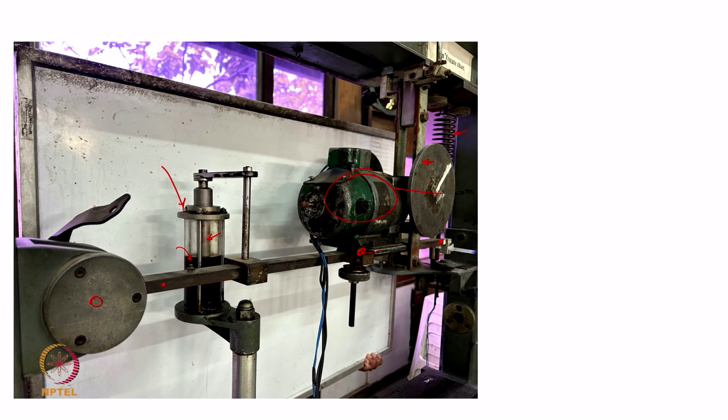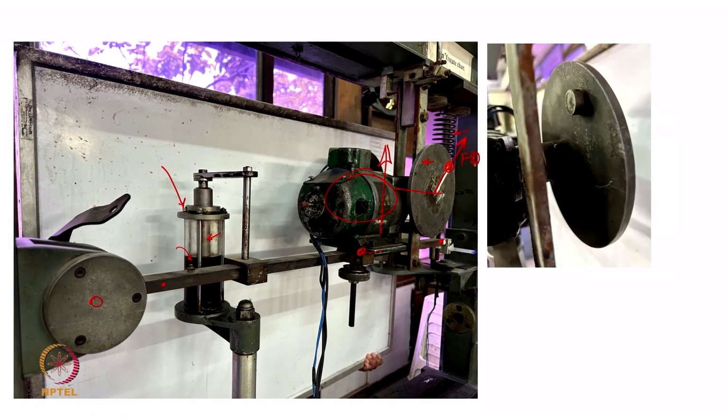These discs rotate about this axis, which essentially generates an excitation force in the vertical direction, and that causes this beam to oscillate as the discs rotate. Why? Because the force due to this unbalance is the excitation force F of t. This picture shows the unbalance that is bolted to the disc here. So, if I take this as an axis of rotation, the unbalanced excitation force will act like this.